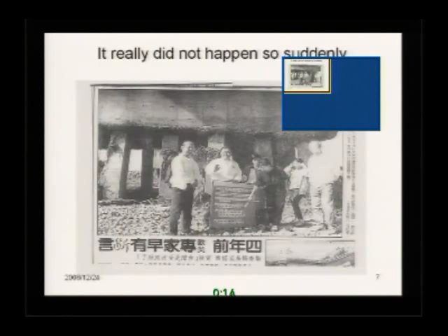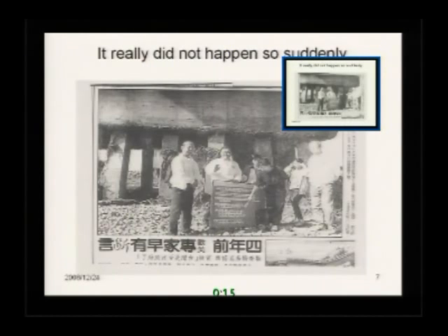Anyway, so this bridge, the different view is that the previous one said the bridge suddenly collapsed, and this picture says 4 years ago, some European and American experts had already predicted the bridge would collapse. The reason is that the piles had been exposed by erosion, by scouring, and the part that eroded is 4 meters, already exposed. So the whole support of the bridge is gone.